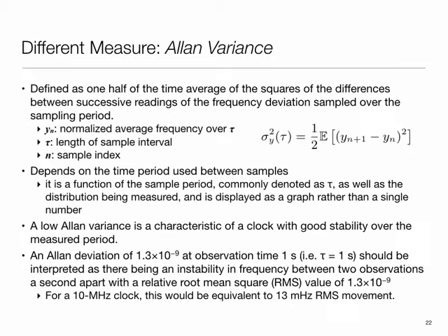What I mean by that is that if I look at the next clock edge, it may be very jittery. But if I look at the average jitter over a long time duration, I may have a very stable clock. Or I can have clocks with exactly the opposite characteristic. They give me seemingly good stability from one edge to another, but then they keep drifting, and over long time intervals the errors build up. But Allan variance, unlike standard variance, allows us to capture that notion.